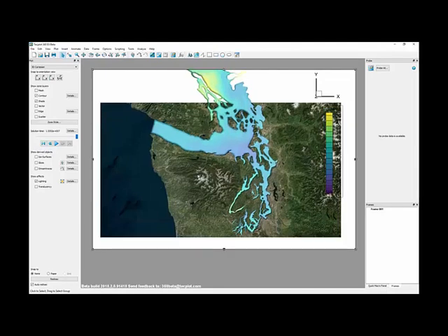contouring. Contouring is a pretty important part of creating presentation quality plots, and choosing the right color map is quite important. So here we've chosen temperature, and we're showing the Viridis color map. This is a perceptually linear color map. It's good for people who are colorblind and gives a nice even view of your data. It has a fairly linear increase of luminosity across the scale. So these sequential color maps are really important.